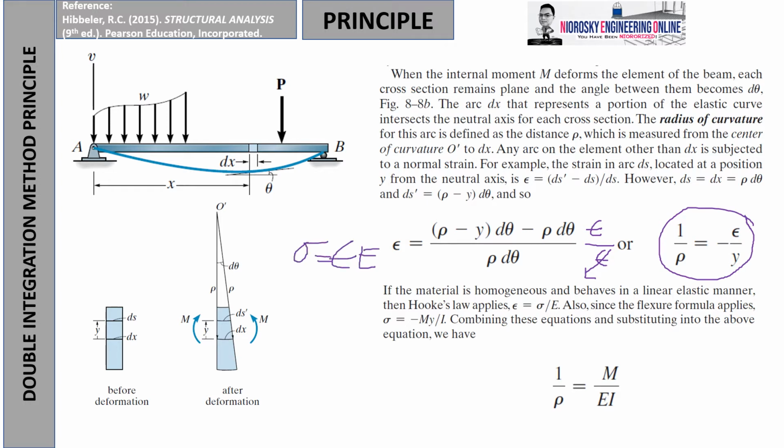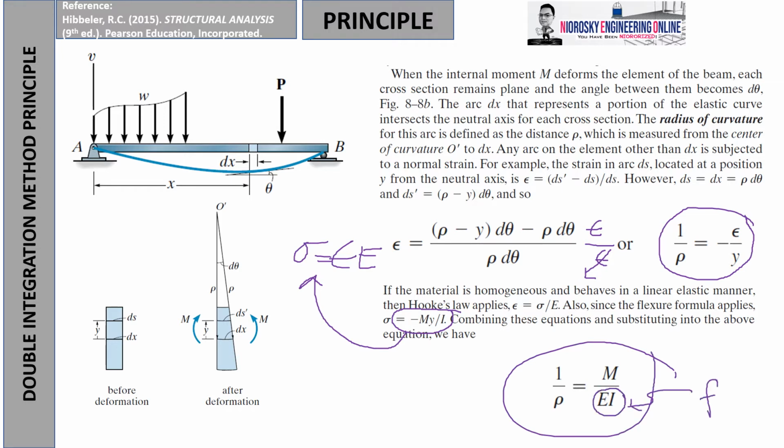So as we take a look and take that into consideration, as we supply this equation, the Mc over I, the My over I inside, you just plug it in there, and then we will arrive at this statement. So EI is said to be again the flexural rigidity. We call it flexural rigidity, okay? So M is the moment flexure, okay? And rho serves to be the radius of curvature of the given segment.